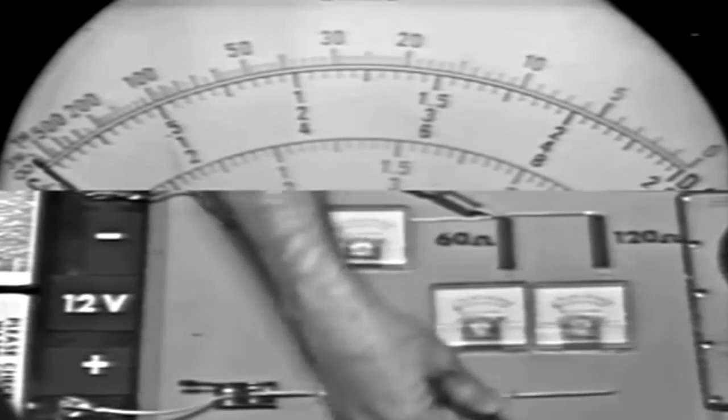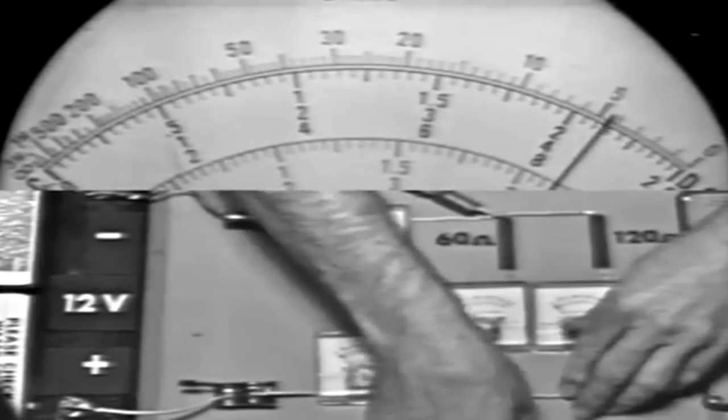So we'll go to the meter, set the function switch to ohms, and we'll use a range of ohms times 10. And as always, we must check meter zero before using an ohmmeter. Touch it up just a little. And as always, before using an ohmmeter, we must remove power from the circuit being tested. So I'll open the switch. Now, to measure total resistance, I'll connect one lead here and the other lead down here, like this.